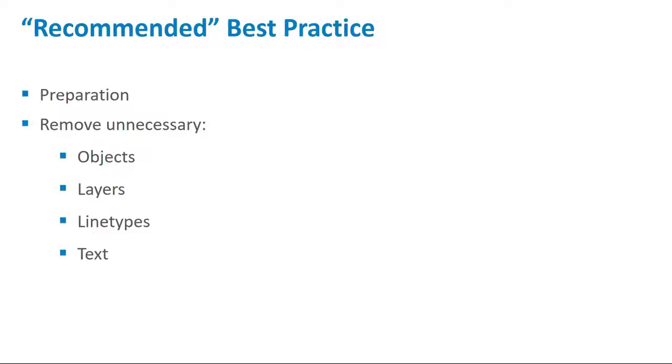Yeah, so the answer to that would be check the scaling units in the DWG first. So do that in AutoCAD. Sometimes if you know what the scaling is without checking it, you can actually specify the units on the import process. But yeah, I'd check it in the DWG first. So open AutoCAD, check everything, objects by layer, remove what you don't need, be sure of the units, and then everything is fine.